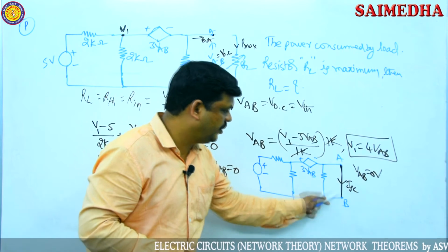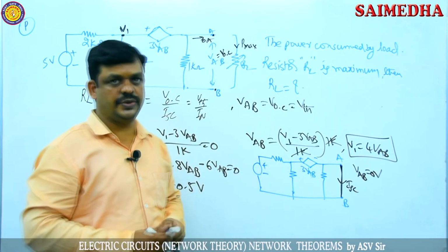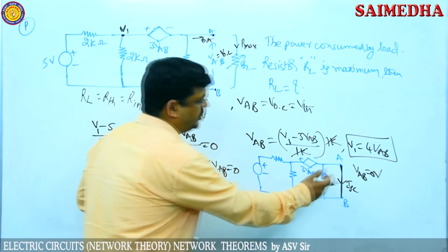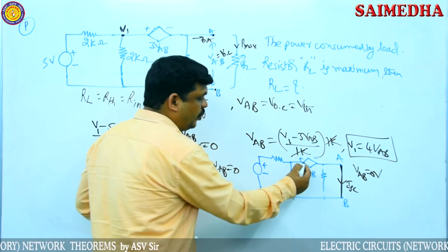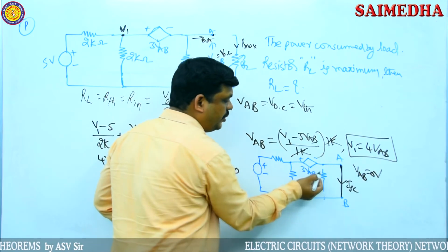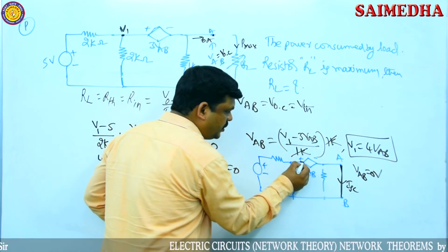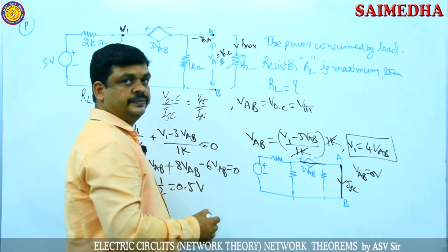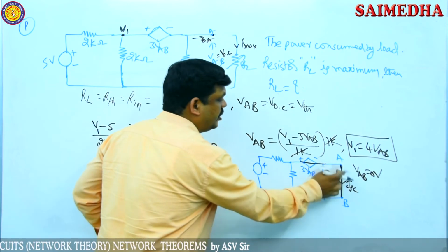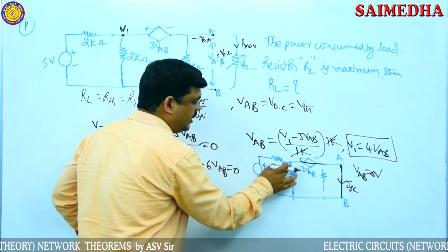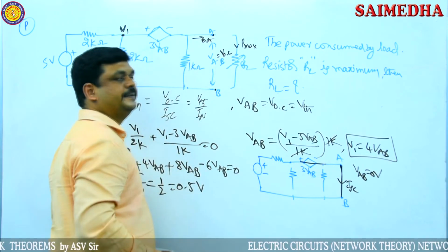Now this branch is 0, then the voltage source is also 0 here. And the short circuit parallel resistance is eliminated here. The voltage source VAB value is 0. If you substitute the 0 value here, the voltage source acts as a short circuit. Then again the complete path is short circuit, so that short circuit and one more parallel resistor are eliminated.